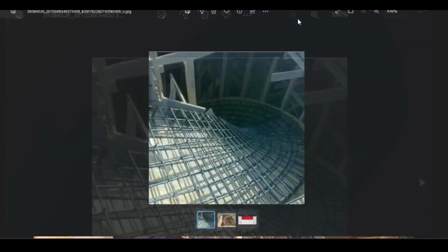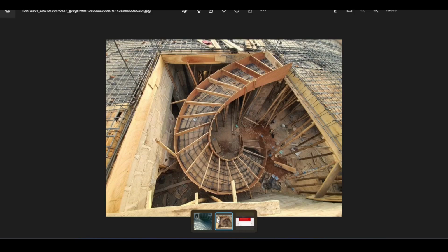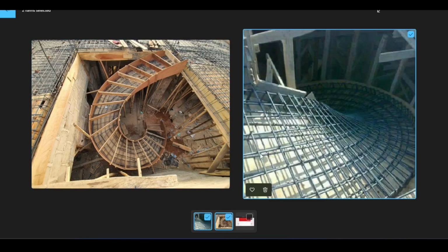Now this is an example of what to do, because the previous one is an example of what not to do. This is a clean example. You can see that the bars are well bent. Of course, the reinforcement might be a little bit exaggerated, but that's not a problem. You can still add more reinforcement if you want. And notice that the 1 phi I calculated was on top, so you need to provide the same thing on bottom. So you can see it's like a little steel mesh, top and bottom, that goes through the entire staircase.